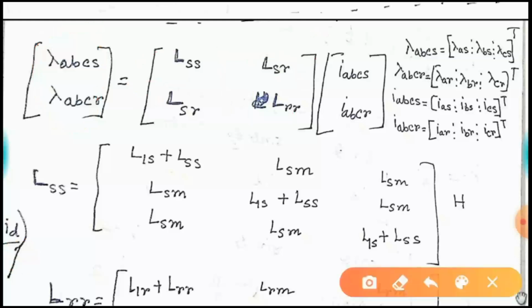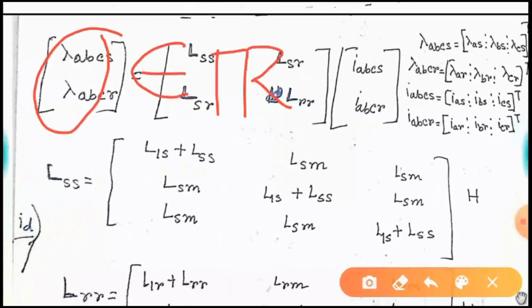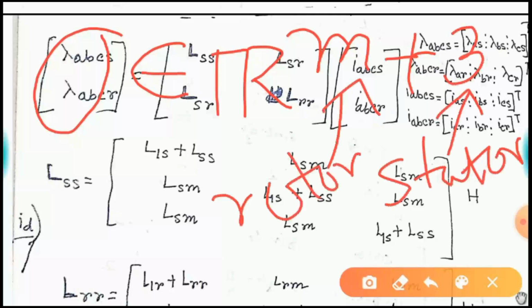This belongs to R6, in the case where you have three-phase rotor. Where you have m phases in your rotor, m may be greater than 3 or less than 3, but in that case the dimension of this vector will be 3 due to the three phases of your stator, and these m are the m number of rotor variables.